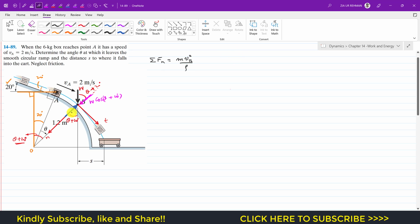Now as we can see that this normal force is acting in the negative n direction, so I will write minus N, and then this component is acting in the positive n, so I will write plus W cos of theta plus 20 degrees, and this will be equal to the mass. So mass is 6 kg, 6 VB squared divided by rho. So rho is the radius of curvature. So the radius of curvature is 1.2. The radius is 1.2 meters. So I have to divide it by 1.2.